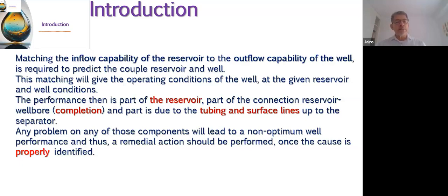Wrongly, people, especially reservoir engineers, say reservoir performance. Again, it's the couple, reservoir and well performance. So this matching will give the operating condition of the well at the given reservoir and well condition.